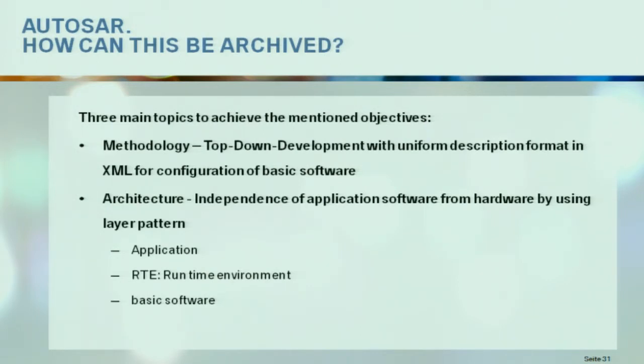And the last issue is standardized application interfaces. With this you can say we always have velocity as velocity, or force as force, or moment as moment, but not as float or as 16-bit float or 32-bit float. So we standardize the interface between the applications.